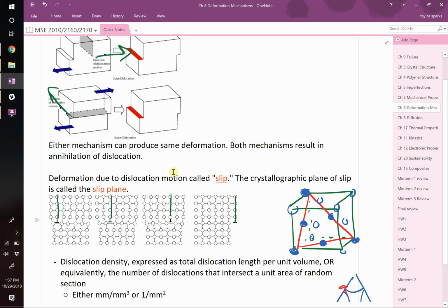That's actually a really high number. It means that no matter which direction I'm applying a load on this thing, whichever direction I'm coming at it from, there's some way where the atoms can slide pretty easily to accommodate that, to get slip. Because of that, FCC metals are very ductile metals. Copper, gold, these things are FCC. They're easy to deform because they have so many slip systems.